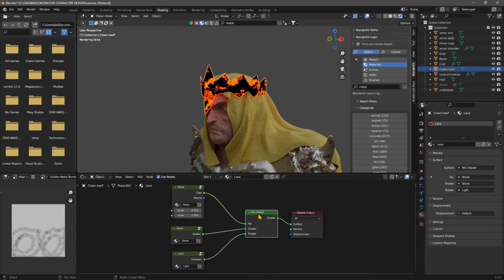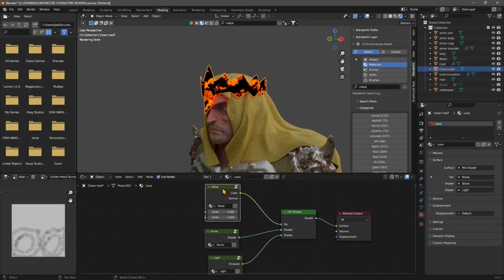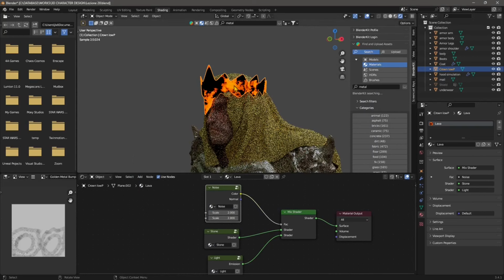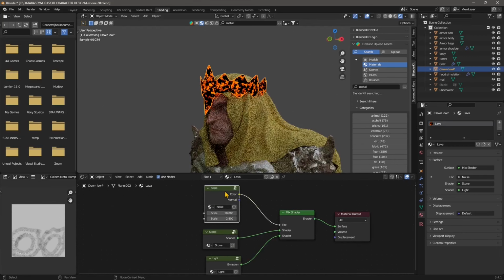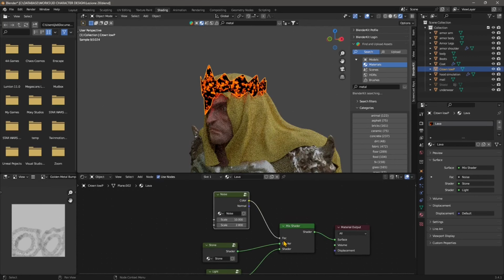This is what emissive materials do. They also create light. If I go to the shading interface, I can see how this material was made, and this is really interesting because I can study how materials are made. You can see we have a mix here. You can mix textures, but you can also mix materials. If you have two different materials, you can mix them together with a factor. So in the Mix Shader node, you have the factor, and then the first shader and the second shader.